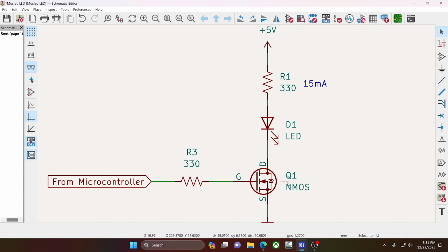The short version, there's capacitance here. What do capacitors do when you first turn them on? You short circuit. So that means lots of current. No good. Use a current limiting resistor on your gate, otherwise known as just a gate resistor.